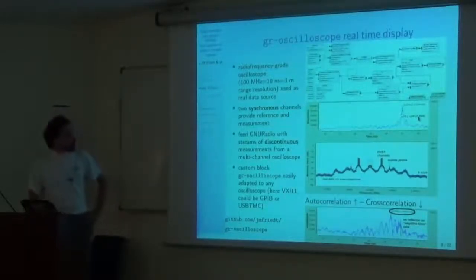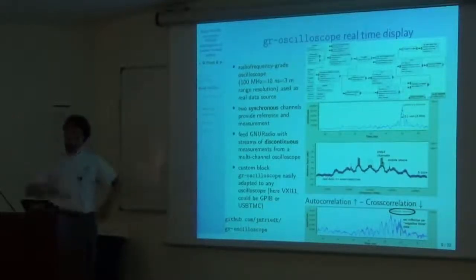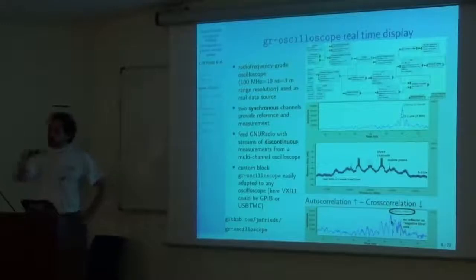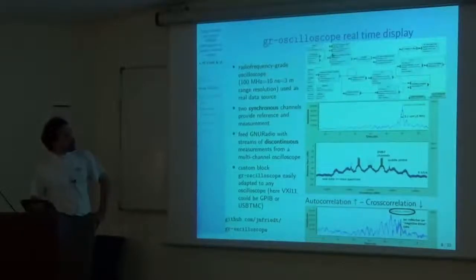And then if I take a cross correlation between my surveillance channel and my measurement channel, so one channel is targeted towards the TV channels, the other one opposite, looking at the targets, you have here the cross correlation. The cross correlation shows some structure, and these structures are all the reflected signal from the surroundings. So it's quite easy to run this setup in GNU Radio.